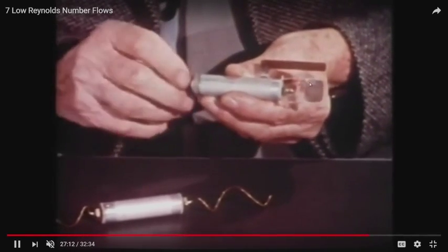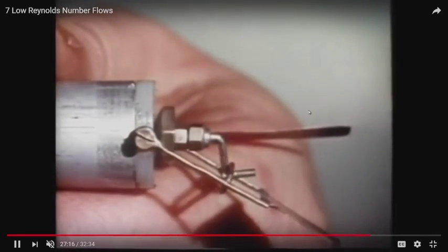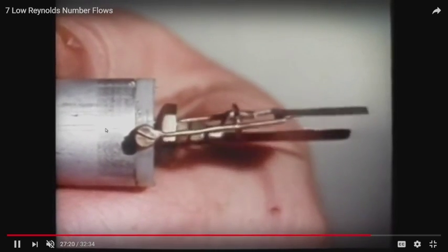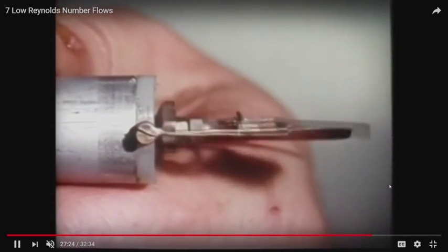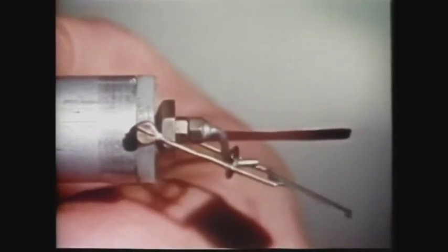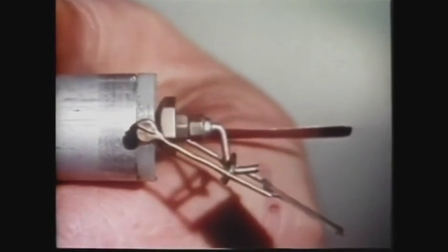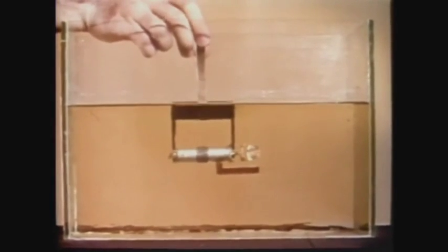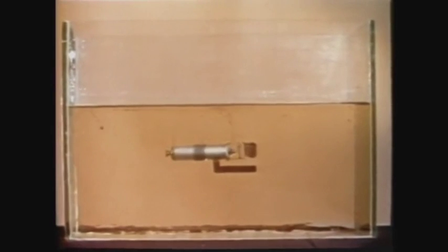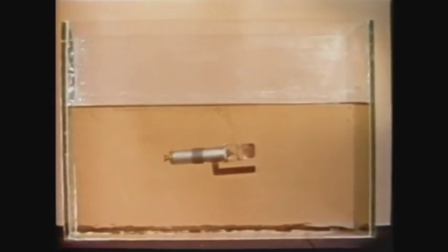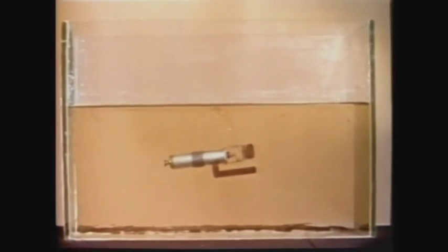He has a turbulent device, right, with the rudder going back and forth, and that propels the system forward, or the little boat forward, and quite effectively propels the little boat. And he's going to put that in water and show you how it works. And it works spectacularly. However, he puts it in a very viscous system, and it doesn't work at all. So the Reynolds number was changed quite significantly here. And you would have to say that from this perspective, this design is a failure. In a sense, you're using turbulent equipment in a laminar application.